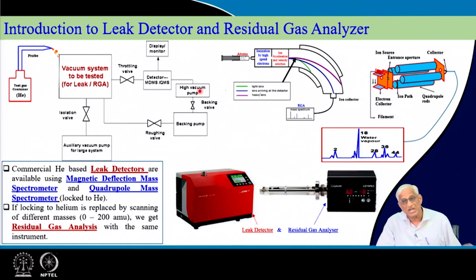If the high vacuum pump was running earlier, let it run also under no load conditions. After all, the detector is a small box and it is leak tight anyway, and these are electrical feedthrough connections, so this is not a part of the vacuum system. These things are already in good vacuum, and these two valves are totally isolating the leak detector part from the rest of the system.